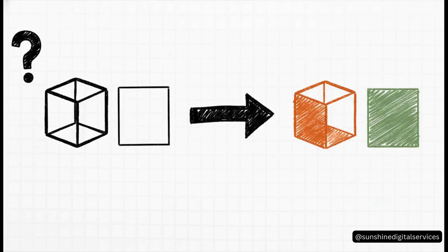But, of course, a shape is just a shape. To make the simulation work, you have to tell the software what everything is made of. You dip into this huge library of materials and assign them. Is this piece of metal copper or aluminum? Is that insulating block made of FR4, a common circuit board material, or maybe Teflon? This step is absolutely crucial for making sure the virtual model acts just like the real thing would.